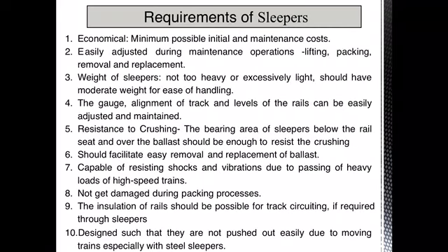Next, what are the requirements of an ideal sleeper? The first requirement is that it must be economical, meaning the sleeper used should have minimum initial as well as maintenance cost. The second requirement is that the fitting of the sleeper should be such that it can be easily adjusted during maintenance operations such as lifting, packing, removal and replacement.